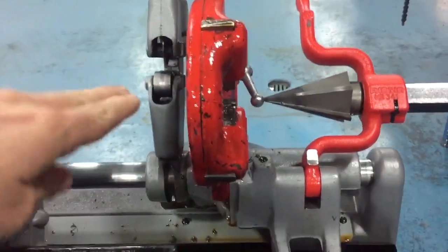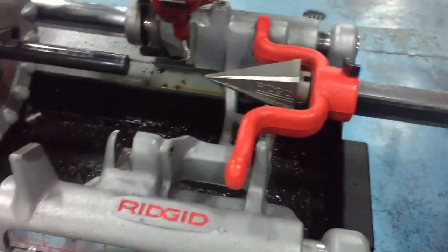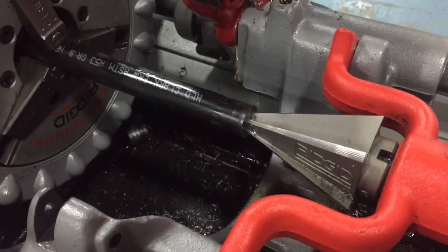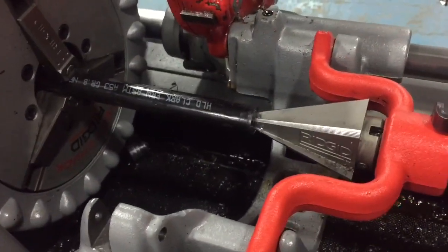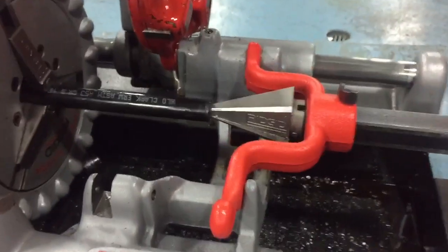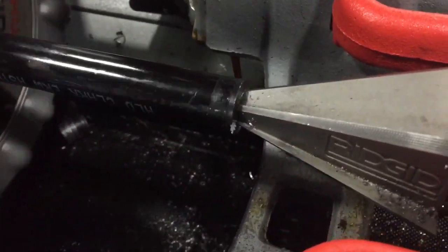So we'll put all the other tools up, they're already up, and we'll bring the reamer down here into place. And then when we are reaming out the pipe here, we're going to use this hand wheel and apply pressure. So what I'll do is I'll go ahead and turn this on. It'll be kind of loud. What I'm going to be doing is pushing the foot pedal and then applying pressure with the wheel here to ream out the pipe. So we'll have a look, and I'll bring you a little bit closer to see that.